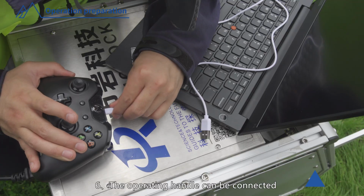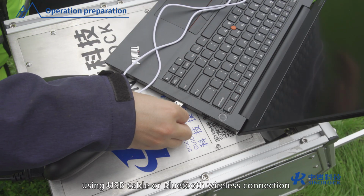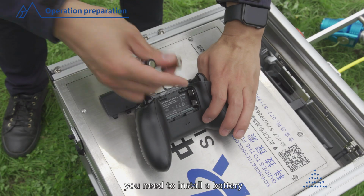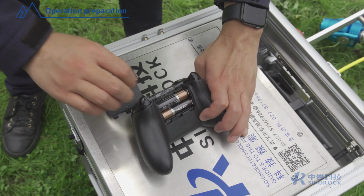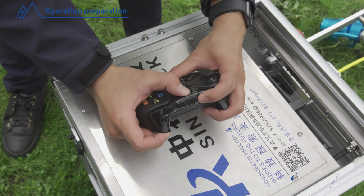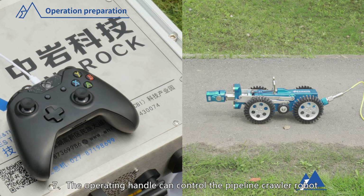6. The operating handle can be connected to the main control computer using USB cable or Bluetooth wireless connection. When using Bluetooth connection, you need to install a battery and turn on the handle Bluetooth switch. Add Bluetooth devices to the laptop and establish a connection with the operating handle. You only need to set up once for each computer.